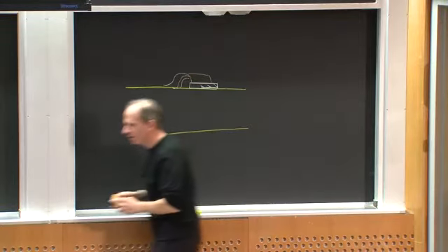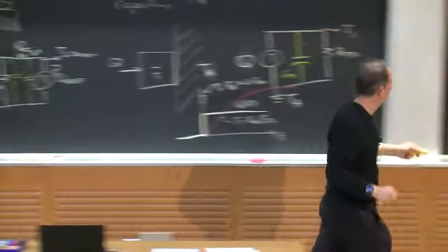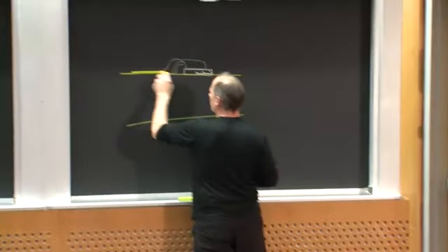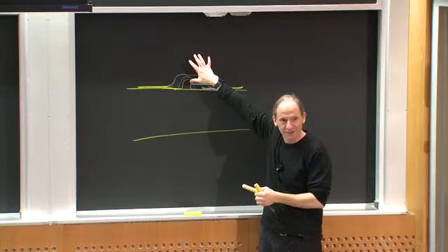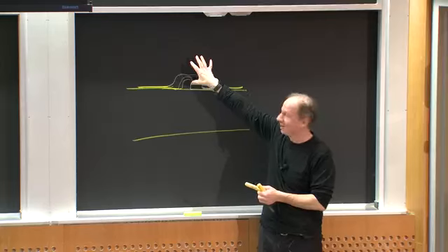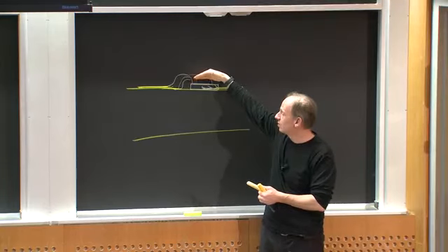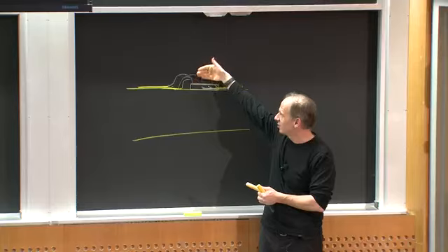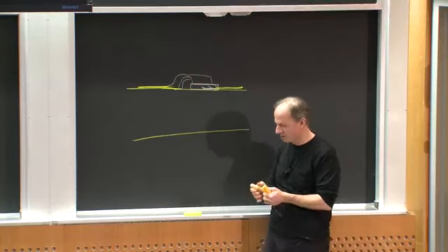And my electrical connections would come off of that. I'd run my gate and my source. I'd have a bunch of wires on the circuit board going different places. So I've made my electrical connection to the device, but now I also need to get the heat out of it. So what do you do? Often, instead of trying to mount the device directly against the heatsink, you mount the device to the board, carry the heat through the board, and then to a heatsink on the other side.